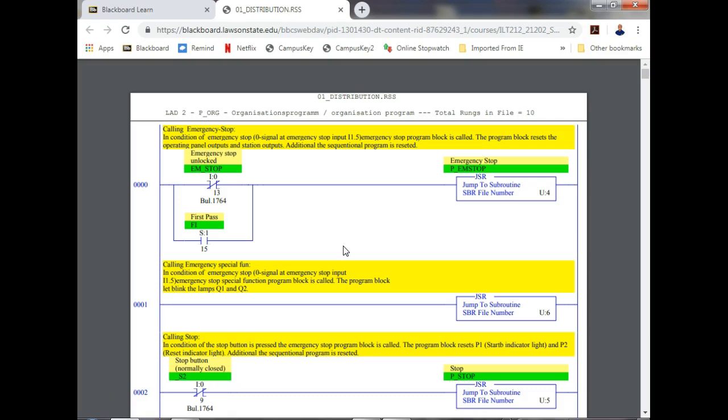And how many inputs do we have on our PLC? Anybody remember? Without the module. That's 12, yeah. So we got 8, and then we got 6 more. I'm sorry, so we got 14, right? We got 14 inputs without the module. So what we're going to find out is all our inputs. I think we'll have to look and see. I think we can pick up on the actual PLC itself. The main purpose that we're going to use this guy for is to pick up, since we don't have enough outputs. How many outputs do we have? Anybody remember? We got, let's see, 0 through 7, then we got 0 and 1 in the second byte. So we got 10 outputs, right?